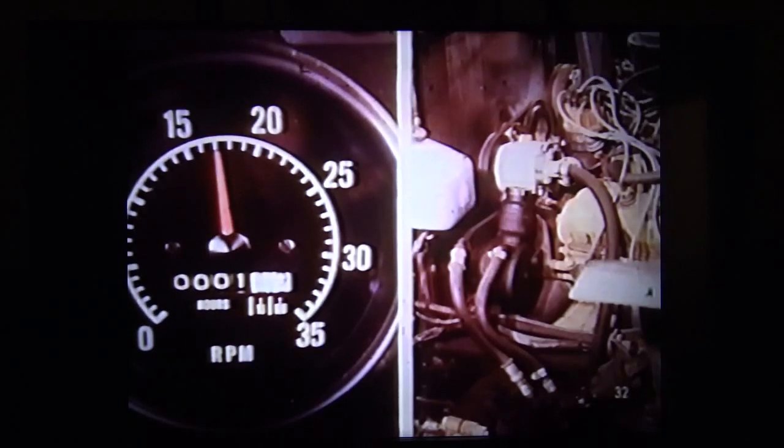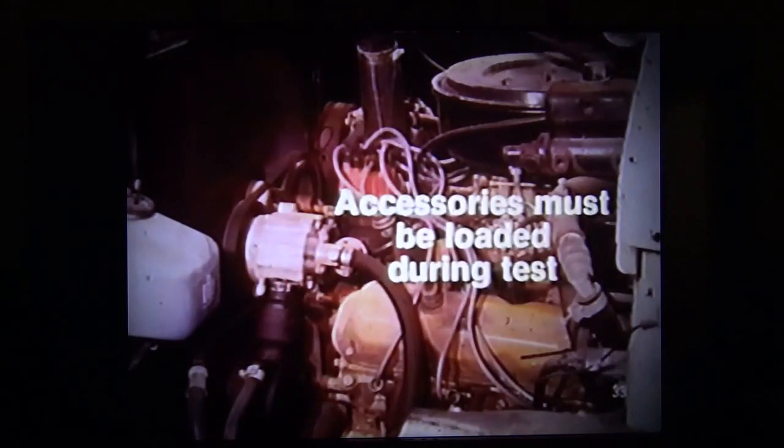If the vibration persists, operate the engine at the critical RPM and visually check the operation of each engine accessory. Be certain the air compressor, freon compressor, power steering pump, and alternator are loaded, performing their function, while you observe their operation. Test the internal operation of the accessories by disengaging one accessory at a time, and then test the result. Repair or replace any defective unit.